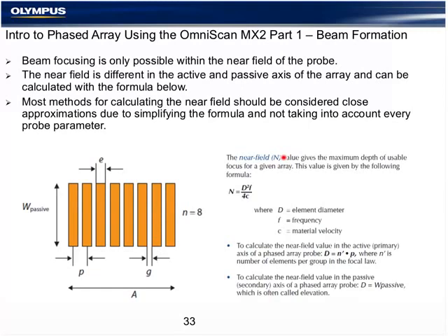In many of our applications, like ASME weld inspection of new construction, the reject rate is designed to be compared to side-drilled holes or notches in calibration samples. To have a phased array inspection generate the same reject rate, you would need to use an unfocused probe by entering a number larger than the near field.